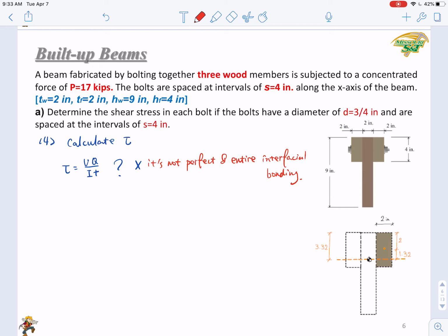However, the shear force can be calculated as in our case 1. Okay, since the shear force is just calculated by balancing the delta F. Right? Since the delta F was, recall in case 1, delta F equals delta M times Q over I. Right?